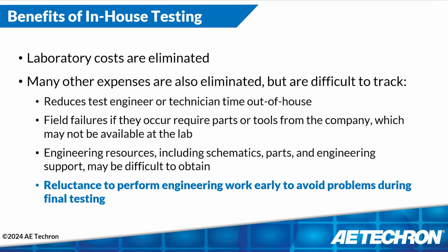As a result, a lot of people will end up doing engineering work earlier in the design and design in these fixes prior to going to a testing laboratory or prior to doing final testing. They say that if you can design in an EMI fix, it's 1/100th of the cost of catching it during final testing.